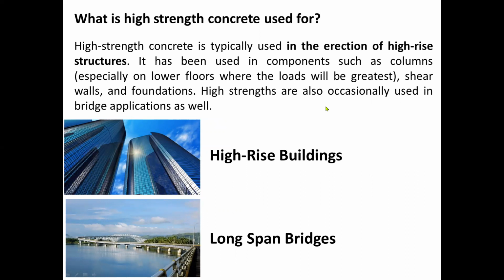High-strength concrete is typically used in the erection of high-rise structures. It has been used in components such as columns, especially on lower floors where the loads will be greatest, shear walls and foundations. High strengths are also occasionally used in bridge applications as well. Mas magandang gamitin ang high-strength concrete sa pundasyon para matatag ang gusali na ating itatayo. Specifically, yung mga poste natin, kailangan made of high-strength concrete kung tayo ay magtatayo ng matitibay na bridges or tulay. And of course, high-rise buildings.